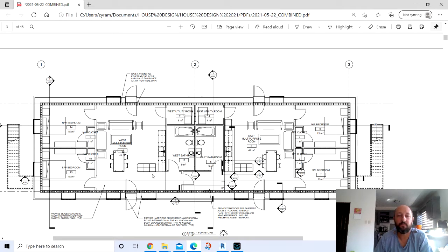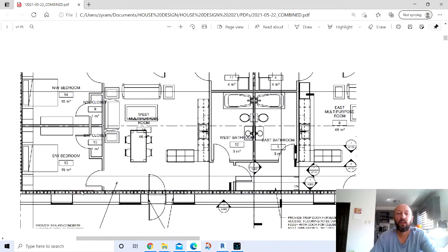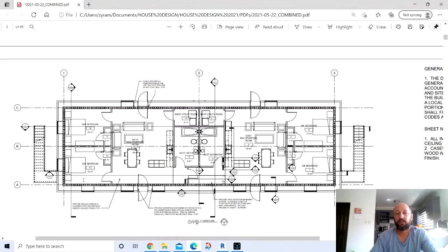So that was one of the reasons. So that's another reason for going with CMU, but also because it's structurally sound. So, in the event that there was a tornado or hurricane or something, then the CMU walls would hopefully protect you somewhat. And also they last. You'll notice a lot of structures that the roof's gone and everything's gone except for the CMU walls or those stone walls. So they tend to last pretty well. So it's got good longevity as well. And they're easy to maintain.